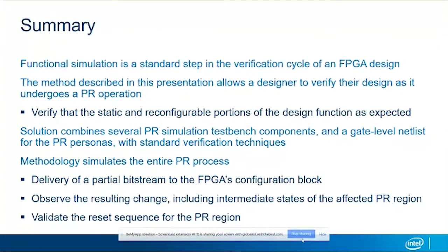Traditionally, it has only been possible to debug problems that occur as a result of partial reconfiguration operation on a board. However, this type of solution to verifying it makes it hard to isolate the source of the problem. The methodology that we've described in this presentation enables designers to simulate the partial reconfiguration operation on a design and to verify that the static and reconfigurable portion of the design function as expected.